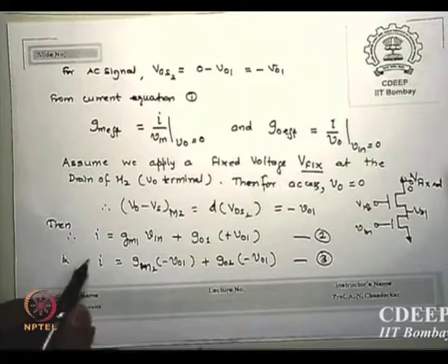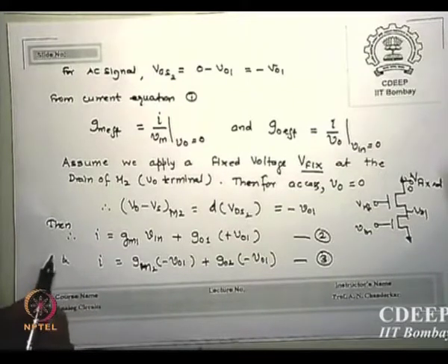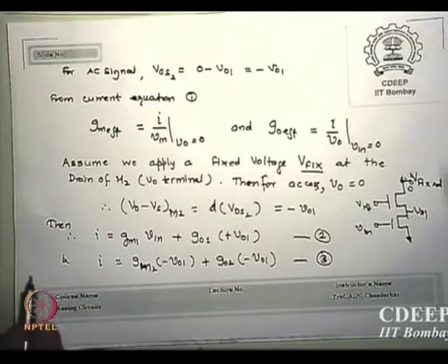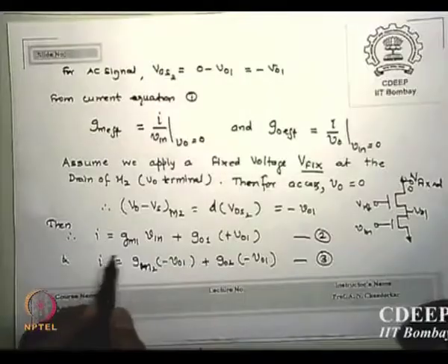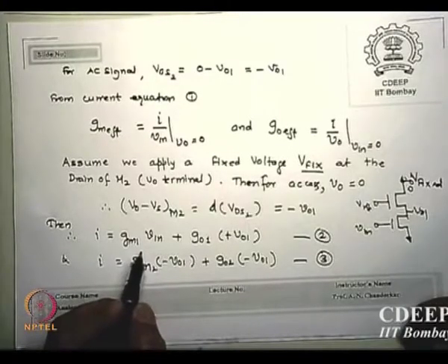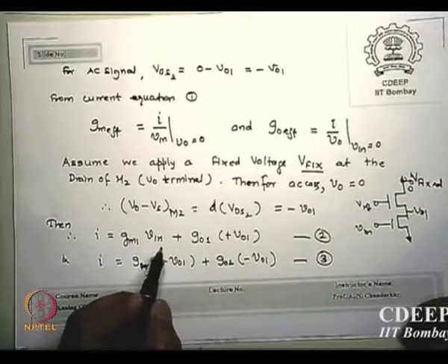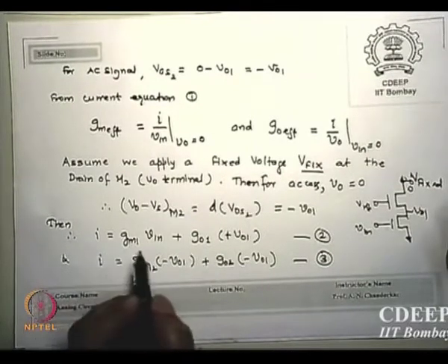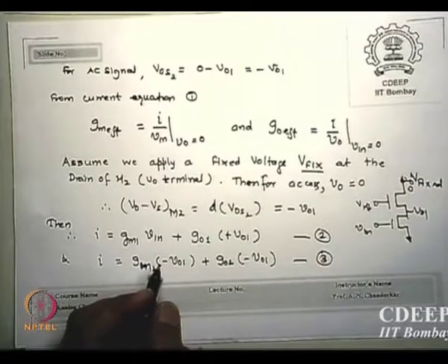Now look back, for the two transistors I write two currents, though I is the same in both transistors. Is that clear? I cannot have two currents in a circuit, there can be only one current I flowing through M2 as well as through M1. So for transistor 1, I is equal to GM1 Vin, same two port network. These are what we call intrinsic values; external resistances we will put later whenever we need in an actual circuit. We want to know intrinsically whether we can break that GM, that is the gain bandwidth limits.